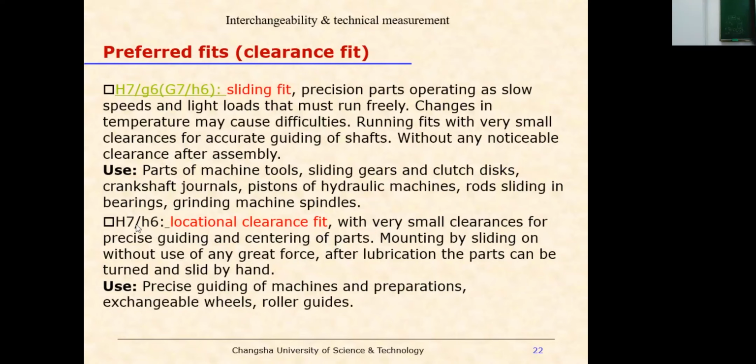So this is the basic hole and basic shaft. The locational clearance fit has very small clearance for precise guiding and centering of the part, mounting by sliding on without use of any great force. After lubrication, the parts can be turned and slid by hand.